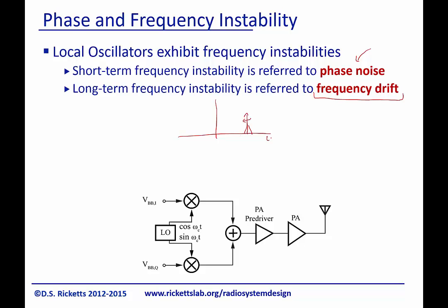Now, this is probably beyond what we're used to thinking about in terms of frequency domain for this course, but what I'm going to do is show you what it looks like in the time domain if we had a clock with phase noise. Imagine I have a clock running through time, okay? And these edges in time move back and forth. So I've got a certain amount of uncertainty here. And this is called jitter. And I think physically jitter is just a little bit easier to understand.